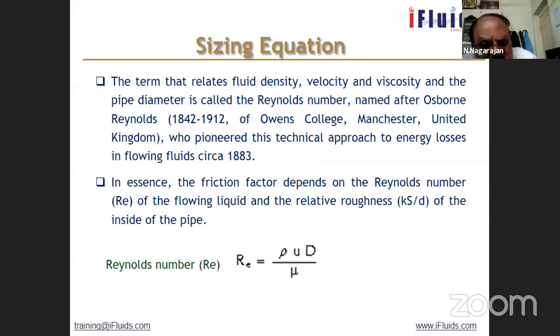Most of the line sizing spreadsheets are connected with API 14E. I told you, API 14E equivalent length tables are there. They are all linked to the Excel sheet.